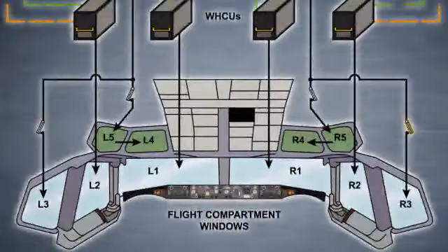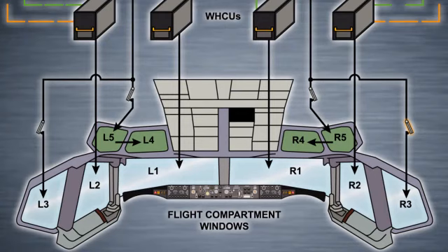The temperature of window numbers 3, 4, and 5 is maintained by 4 separate thermal switches. These thermal switches open and close to maintain the correct window temperature. The switches close to allow current to pass, and open due to thermal expansion of their corresponding windows. There is one switch attached to each number 3 window, and one switch attached to each number 5 window.